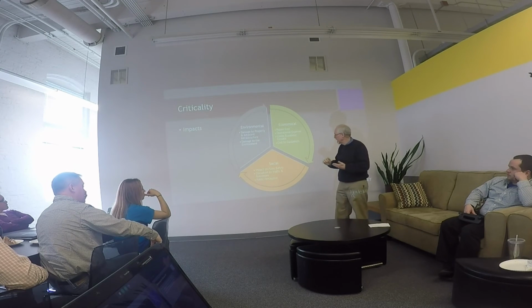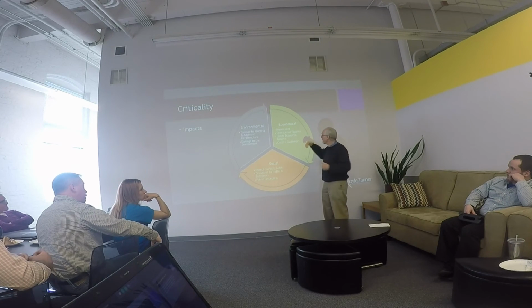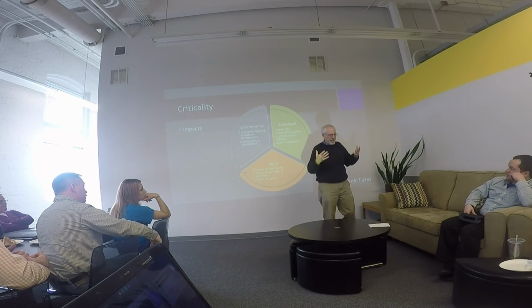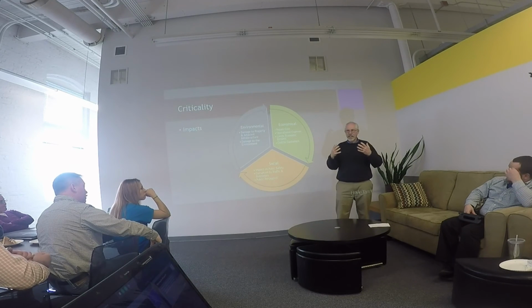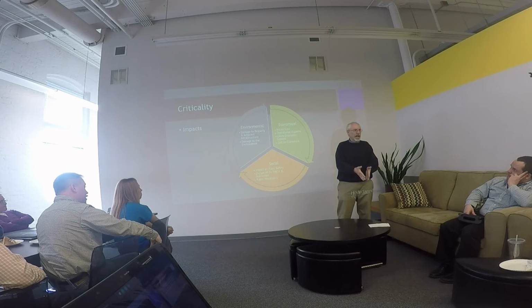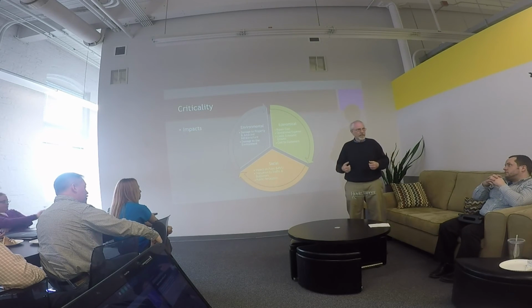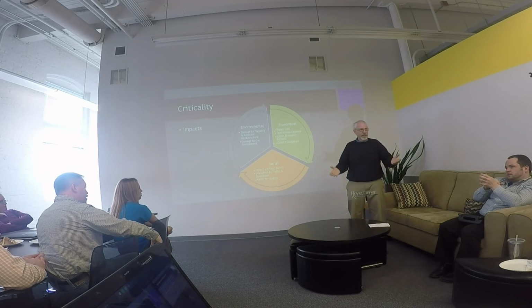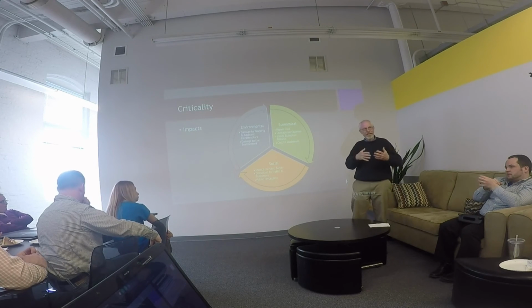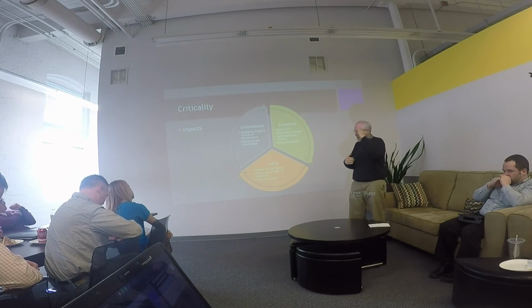Which could be an oil spill. That would be an environmental impact. Okay. Economic. When you look at an asset, is it difficult to repair? If you have a pipe that's 16 feet down, that's a higher risk and a higher financial repair if it occurs. But if it's down in Florida and the water pipe breaks, you probably go out there with a hand shovel and dig it up, and you're able to repair it. So the cost of repairing may impact what the criticality of that asset is.